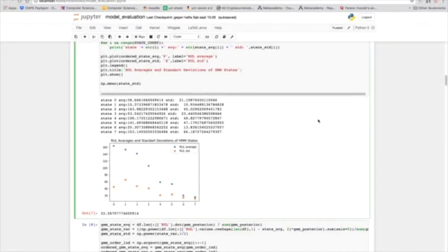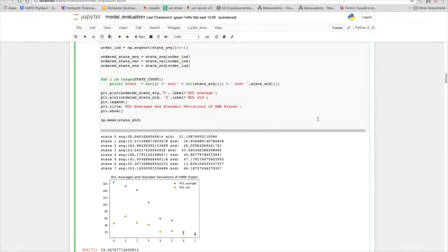Moving on to the model, I built a hidden Markov model with 8 states to capture the system's behavior and trained it with the training data. After the training, I had these 8 states, ordered from the big remaining useful life to the smaller one, which means from a healthy state to a worse state here.